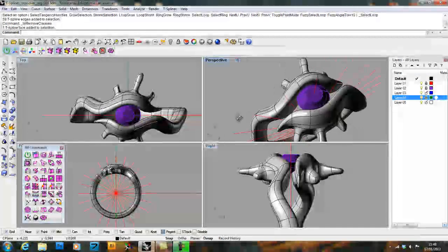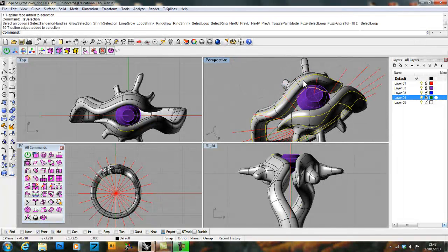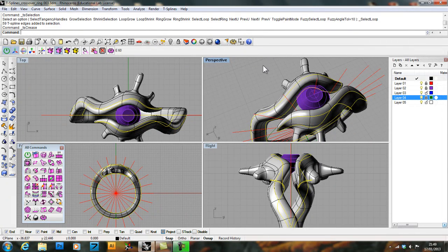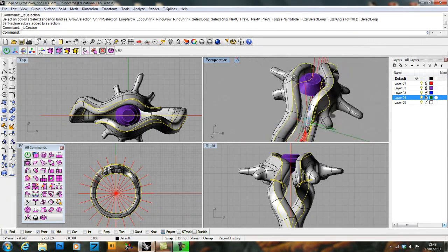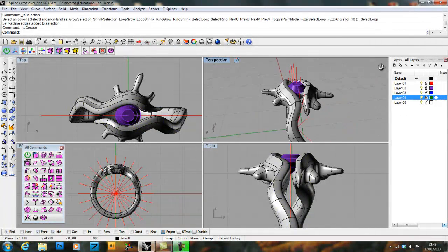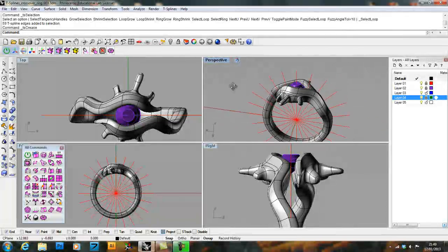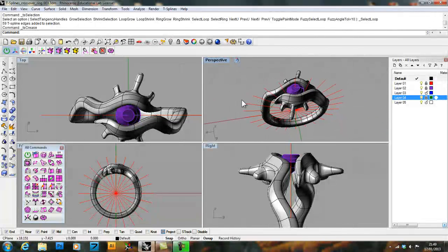Another thing you can also do to the surface as well, might be interesting, is to grab one of these curve seams or the whole edge segment set, the whole loop, and I can apply a crease to it that adds a bit of extra level of sophistication to the shape itself. Gives you a little bit of an idea just how far we can push T-Splines and just how complex this program can really become.